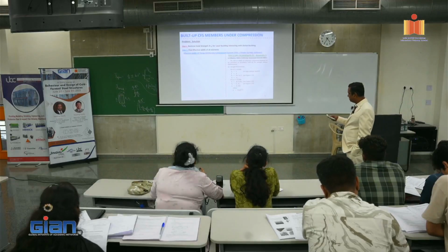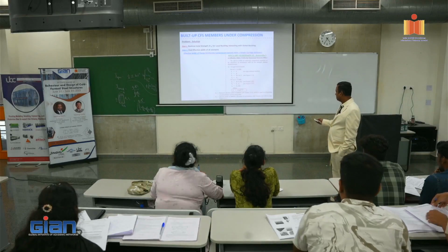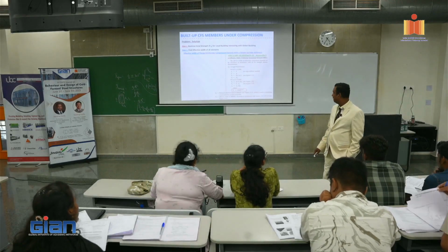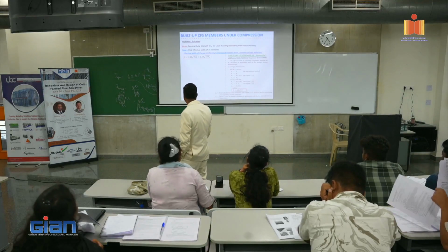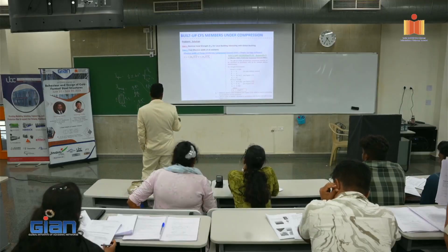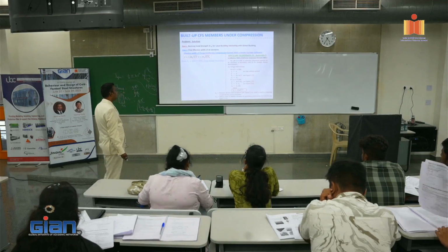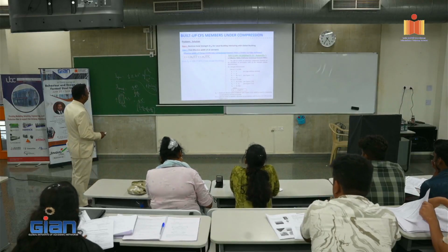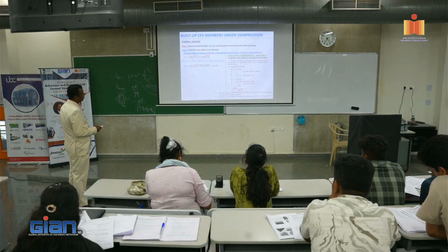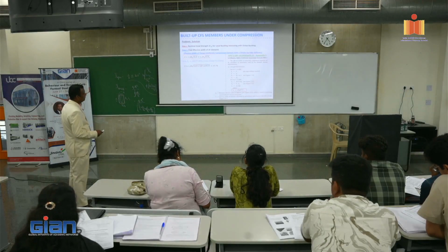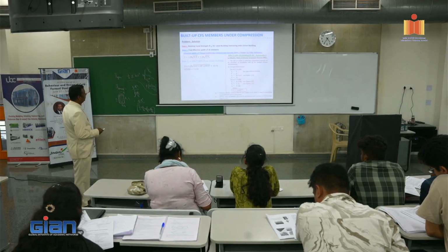Now, the question is, what is S? S is given as 1.28 into root of E by F, where F is nothing but the nominal stress that we previously calculated, Fn. So Fn equal to 259.77 from global buckling. When we put 1.28 into root of 2.03 into 10 power 5 divided by 259.77, we get 35.78 as S. Now what is 0.328S? It is given as 11.74.